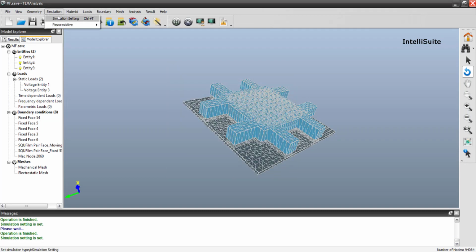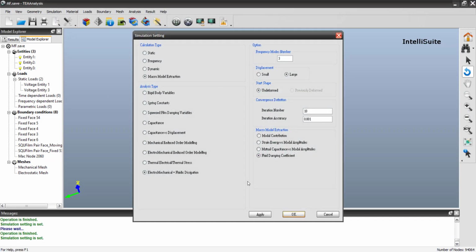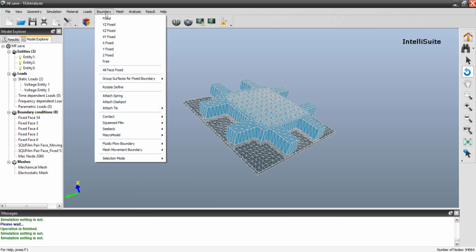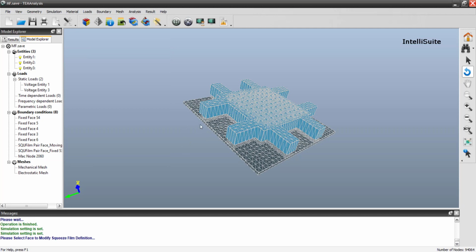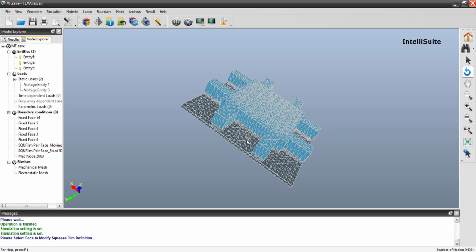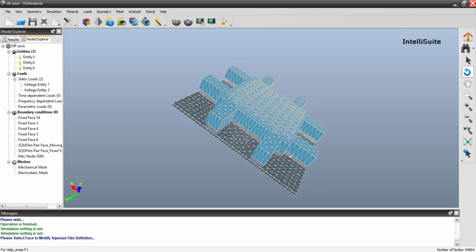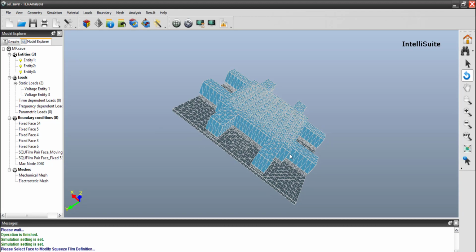Now we'll have to say what the fluid below it is. So the fluid damping characteristics have to be defined. So we select this fluid damping coefficient and then go to squeezed film, moving phase. So which is the moving phase here? The moving phase is the top surface. So that green entity which is below is the moving phase.